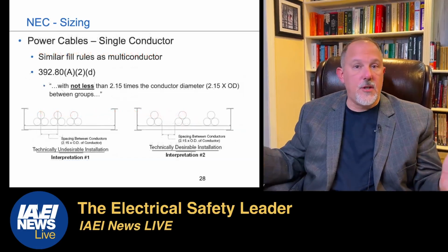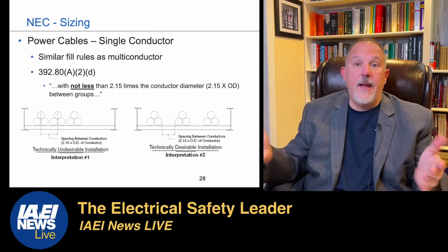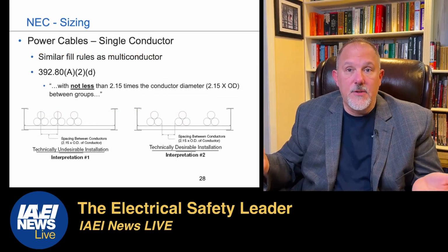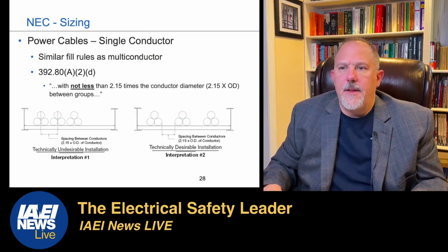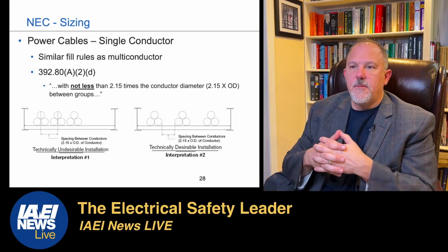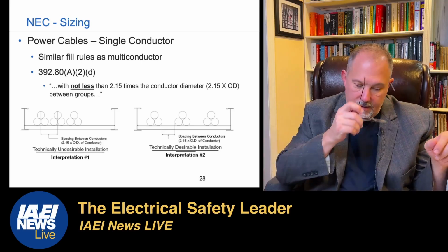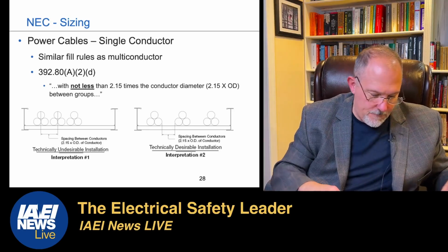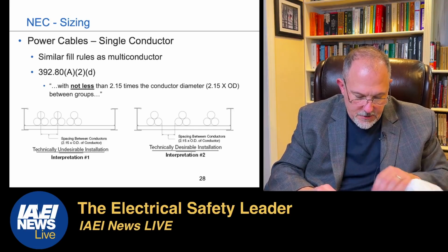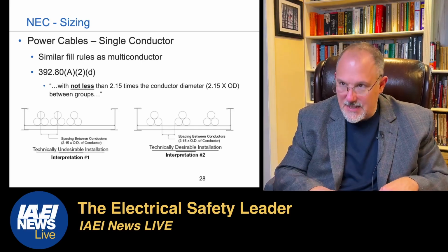That's going to all determine the size, and then the weight is going to be associated with that as well, right? Now, these are your power cable single conductors, similar fill rules as multi-conductor. 392.80(A)(2)(d). 392.80, ampacity of conductors.